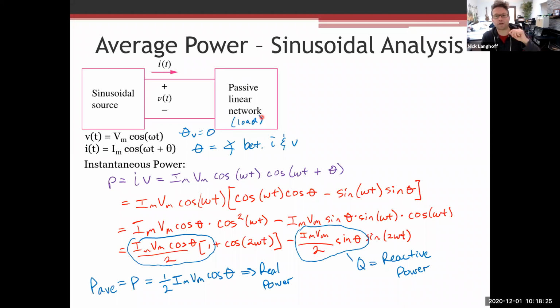So for example, if you wanted to actually turn a motor to get a Tesla car going down the freeway, it's the real power that is going to propel it down the freeway. There could be reactive power interchanging between the three-phase motor controller circuit pulling from the 480 volt battery pack, synthesizing AC signals and delivering that to the three-phase inductive motor.